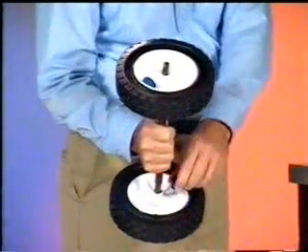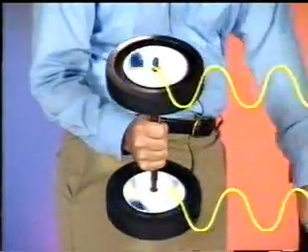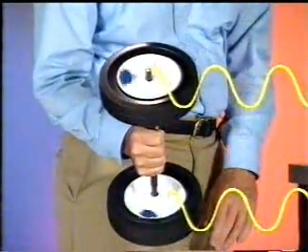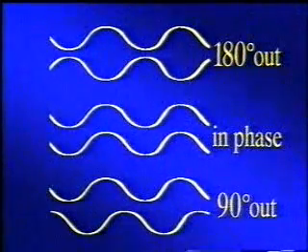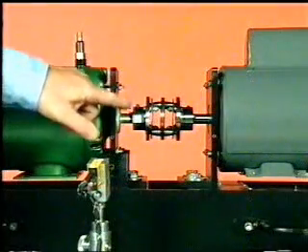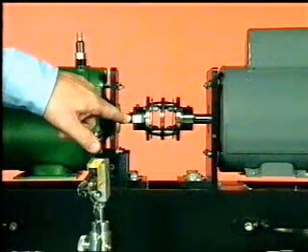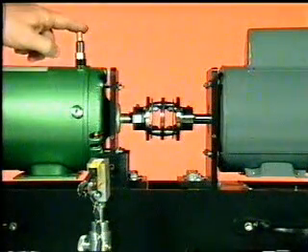When one weight is moved 90 degrees and the motion is traced, the sine waves will be out of phase by 90 degrees. With this example, we have been looking at the phase or relationship between the two unbalanced wheels. On a machine, the phase is normally measured from a fixed or reference position on the rotating shaft to the peak of vibration at the sensor.